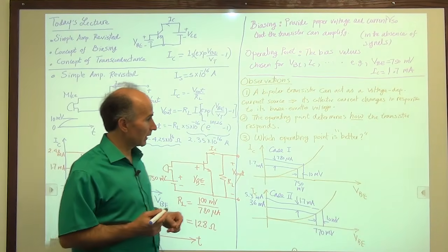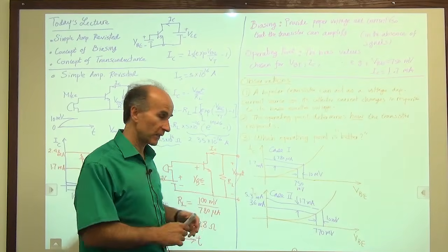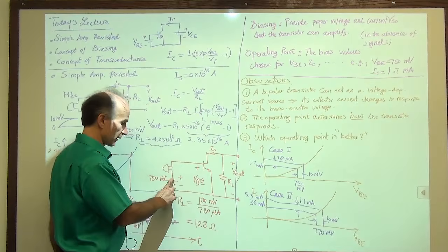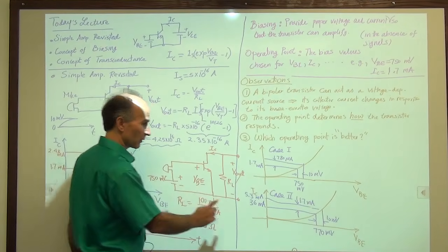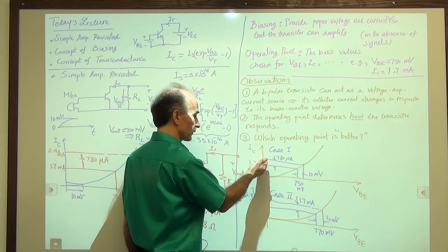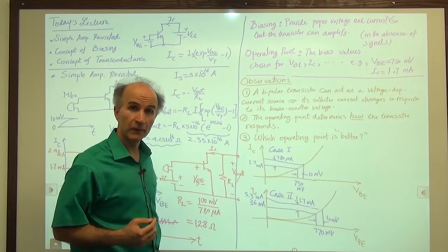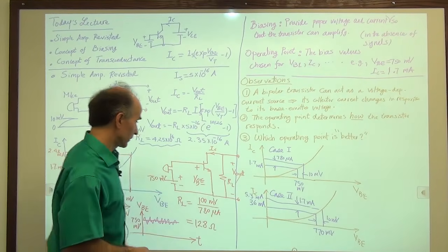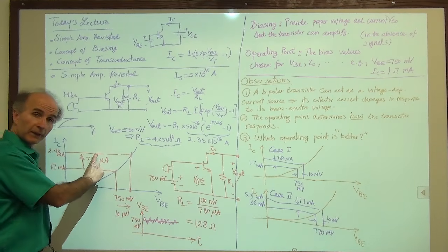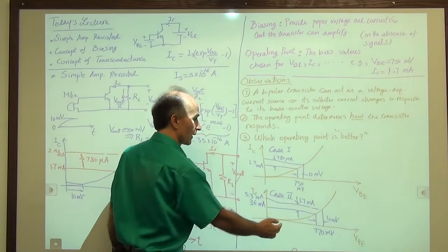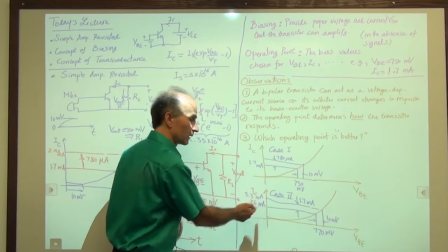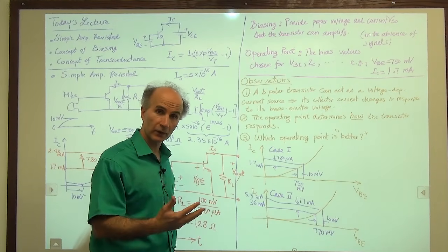All right, so what we see is a simple trend. As the bias value of the base emitter voltage, this battery, assumes larger values, the collector current becomes more sensitive to the base emitter voltage. Here, we got nothing. It was very small. Here, we got something. Here, we got even more. So as we give it a greater base emitter bias voltage, the sensitivity, the response, the change in the collector current increases.